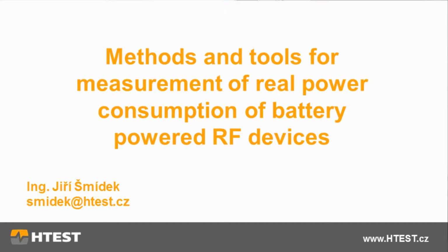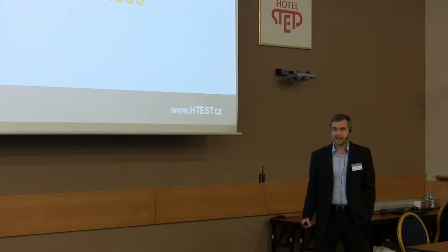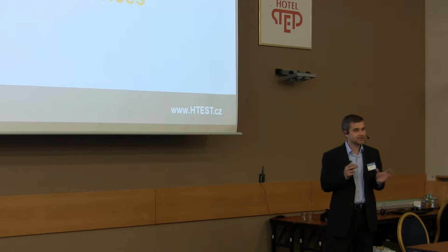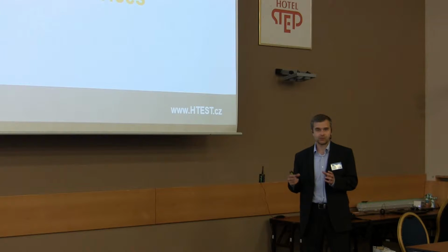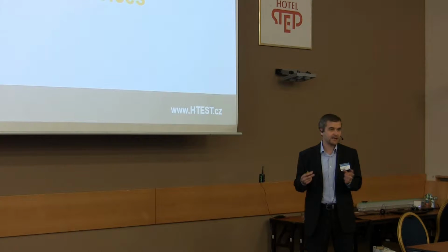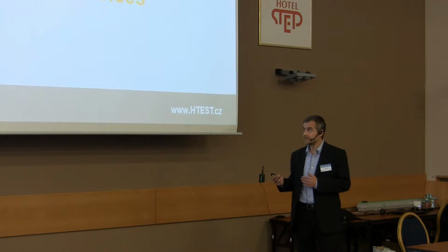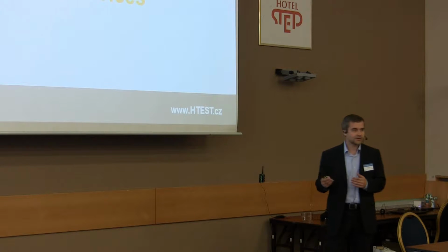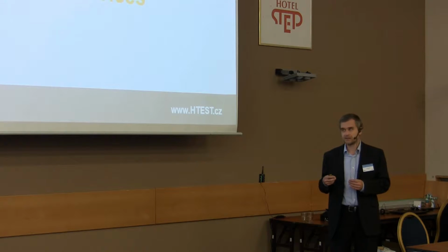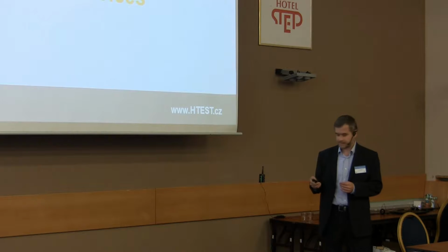I would like to show you some possibilities of how to measure power consumption of battery devices. If you measure it better, you better understand each state of the battery device and you can optimize it in hardware and software better. As a result, you can lengthen the working time of the battery device.